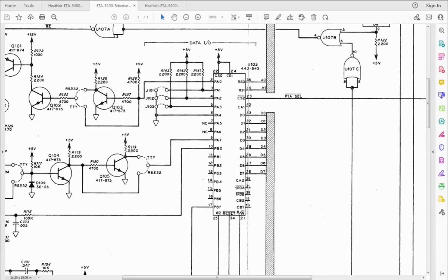So on the Heathkit, they didn't even put a DIP switch in, but you have to hardwire these jumpers. The processor comes in and reads these bits, and depending on the state of the three jumpers, does a table lookup and goes, oh, you want 110 baud. All right, so be it. It's not used for anything else.